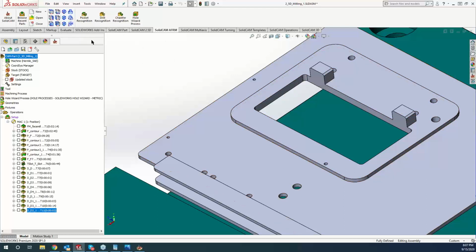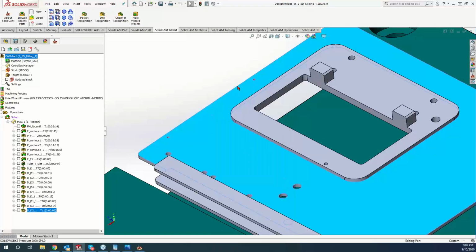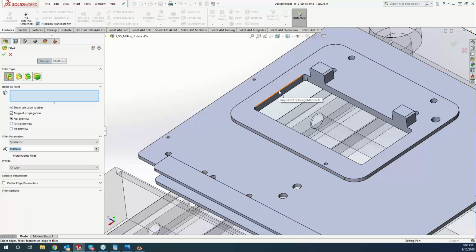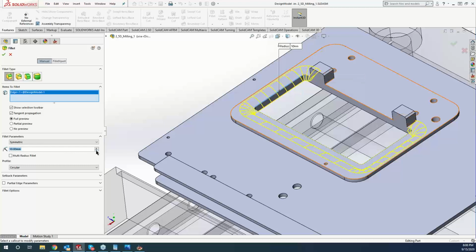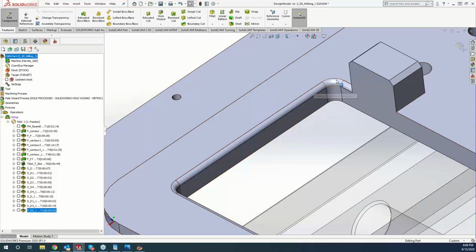Yep, but are you talking about it's going to be running perpendicular, yes, to the plane? So what I say is, if we did a fillet like that, it would ignore. It's quite large. Let's do a 1 millimeter. So if we had a fillet on here, it would ignore this line right here as a fillet, not an internal fillet or an external fillet.